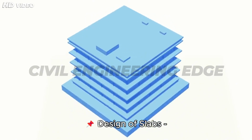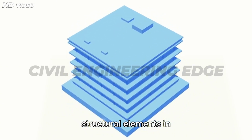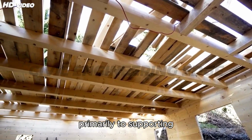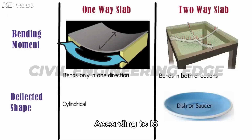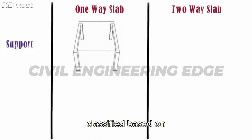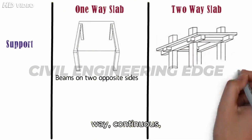Design of slabs. Introduction as per IS code. Slabs are essential horizontal structural elements in any building system. They transfer loads primarily to supporting beams or walls and play a major role in shaping floors and roofs. According to IS 456:2000, slabs are classified based on support conditions and aspect ratio into one-way, two-way, continuous,